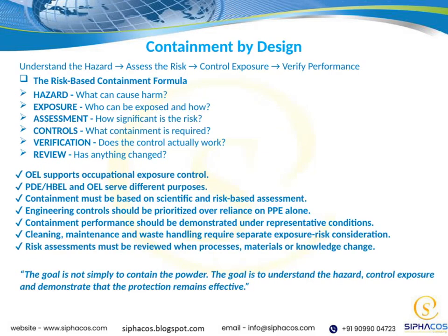When we talk about containment, it's not just about keeping the powder inside a box. It's about really understanding the hazard, controlling who's exposed, and proving that our protection works. We rely on occupational exposure limits to guide control, but those limits serve different purposes than other thresholds like PDE or HBEL. Containment has to be based on solid science and risk assessment, with engineering controls taking priority over just personal protective equipment. We also need to test containment under real conditions, and remember, cleaning, maintenance, and waste handling bring their own risks. Finally, risk assessments aren't set in stone. They need updating whenever processes, materials, or knowledge evolve.